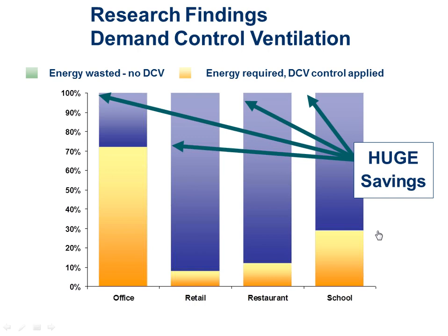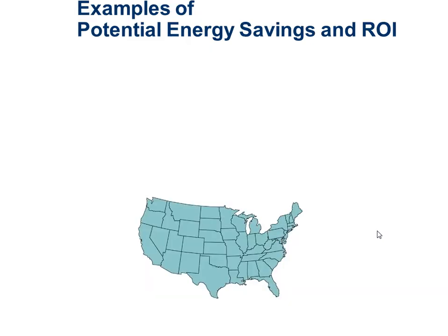They're bouncing all over different rooms. When I design a normal school, I've got to design every room for the maximum number of kids and provide that ventilation air there. But if I track with the CO2 levels what rooms they're actually in, I can throttle many of those rooms back when they're not being used. When there's no kids in the gym, I can throttle it back to some ultimate minimum level that's below the code minimum. Same kind of thing with the classroom or the library or whatever. So it's really more to do with the kids moving around the building than it is that they're not actually showing up for school, although that does happen too.